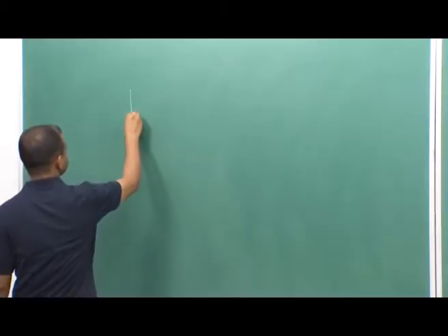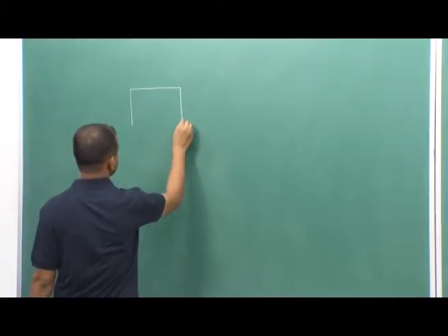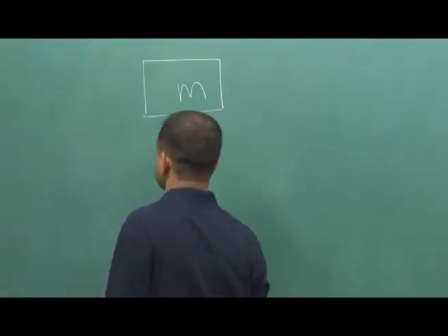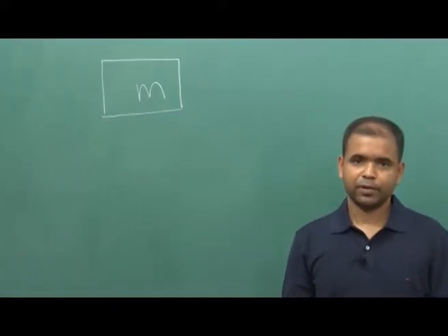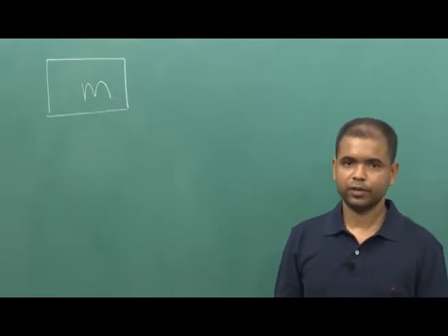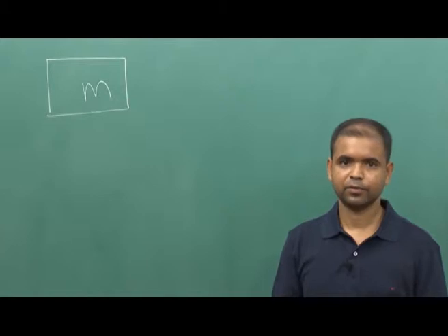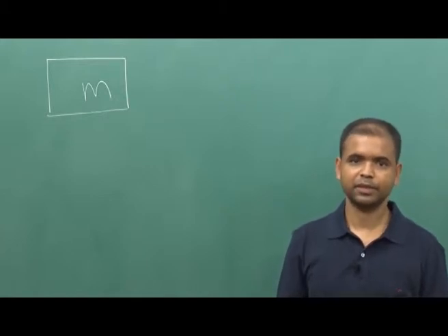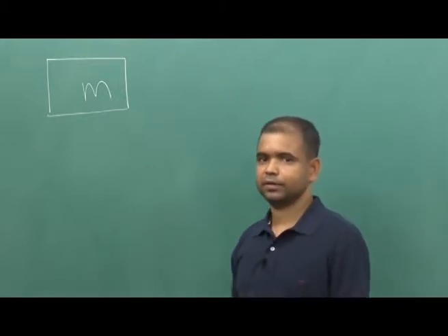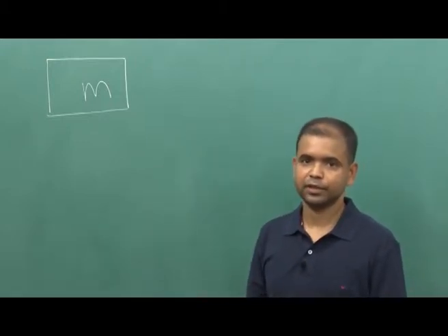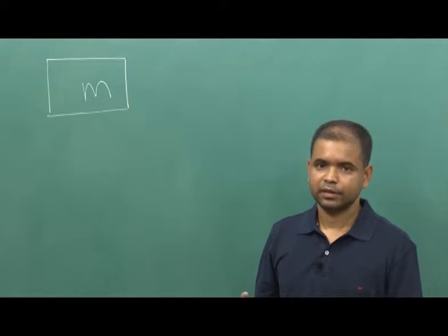In the spring, mass, damper system, we have three basic elements. The first one is the mass. Whenever we apply a force on a body, the net summation of the opposing force and the applied force is 0, and due to the mass there is an opposing force, and this is the inertial force.